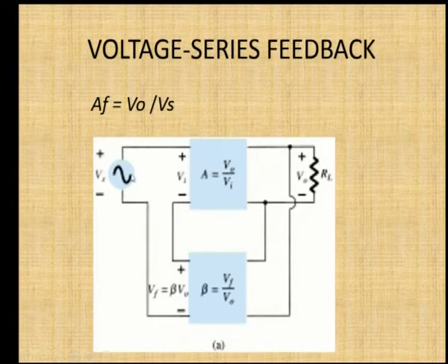About the voltage series feedback connection, we know that the term voltage presents that the output is the voltage signal, and if it is the voltage signal, the connection must be parallel, because across any parallel ohms, the voltage is equal. So, if you want to take voltage, you have to take it across the parallel connection. If voltage is given as the input to the feedback network, the connection must be a parallel connection. So, for voltage it is parallel.